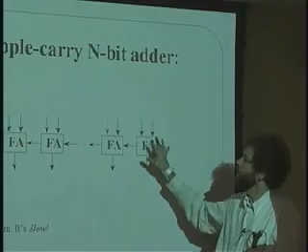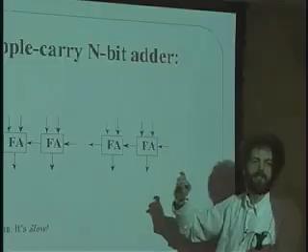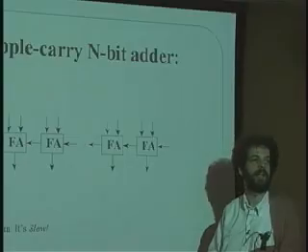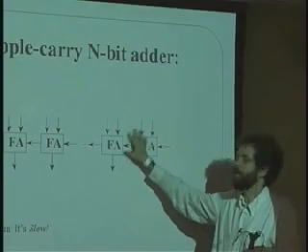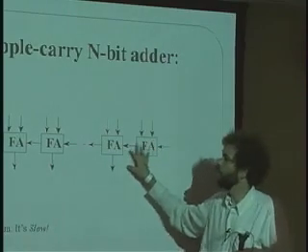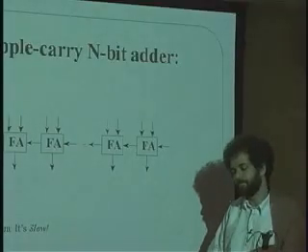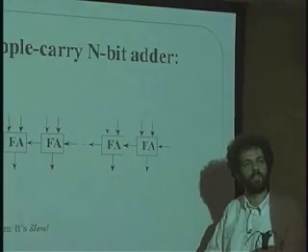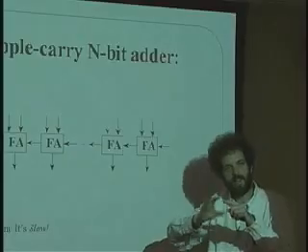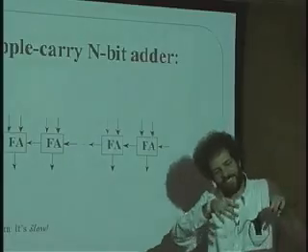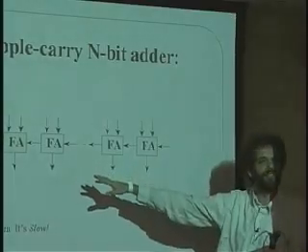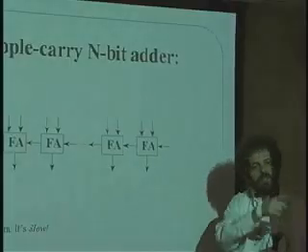But in this simple case of just the ripple carry adder, first of all, it has 2 issues. One is that it's highly dependent on what the numbers are that you're trying to add. If the carries only happen on the right-hand side, then the adder will be fast. But if the carries are required to go all the way through, it's like an odometer on a car, and it says all nines, right? And you go over that last mile, and that last one turns the next 9, and that 9 turns the next 9, and so on until it finally goes all the way to 0. That's kind of how this full adder system works, the ripple chain, but it takes a long time for it to carry over.